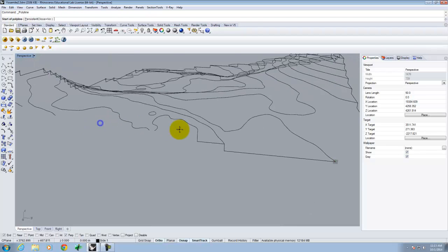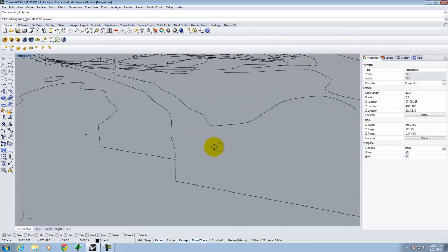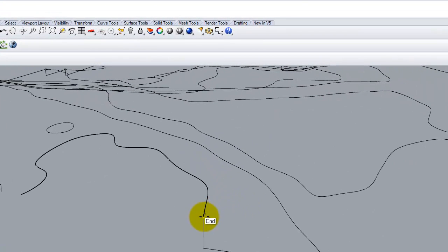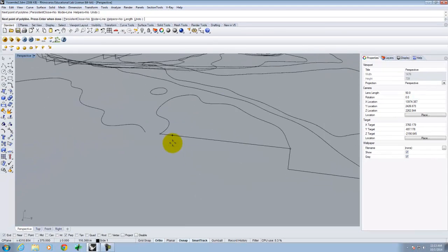Okay, so here's a good example of something that can happen as we're working through this piece of terrain. I have one contour that comes around and it ends right back to where it was. Okay, so when that happens, I'm going to go, and I'm on the upslope, I'm going to go straight across. Okay, now here's another good place, right? This is again the same contour, so the logical thing would be to continue going straight across, except that the contour cuts back the way I am, so I actually have to go down, over, and then back up.